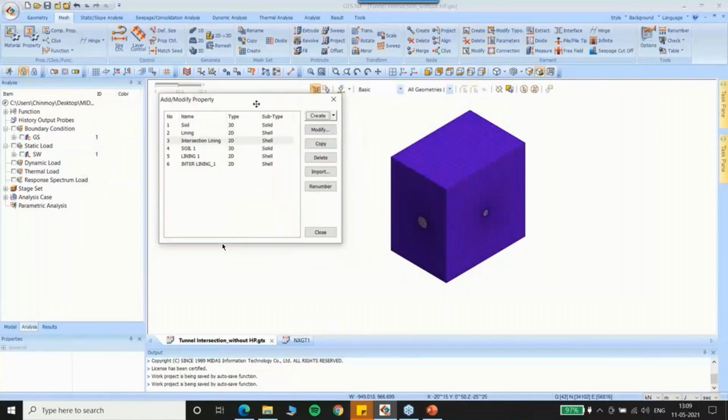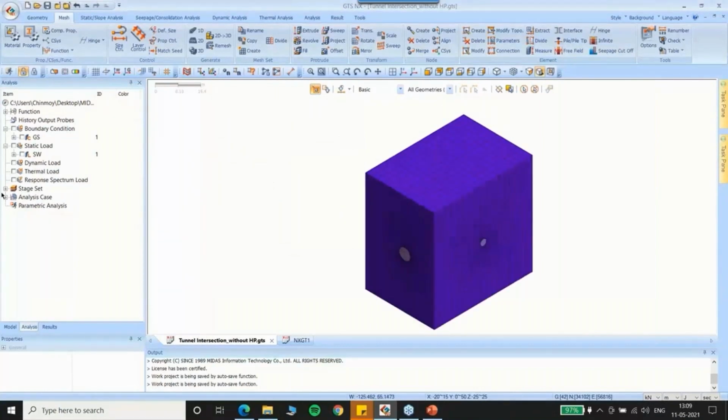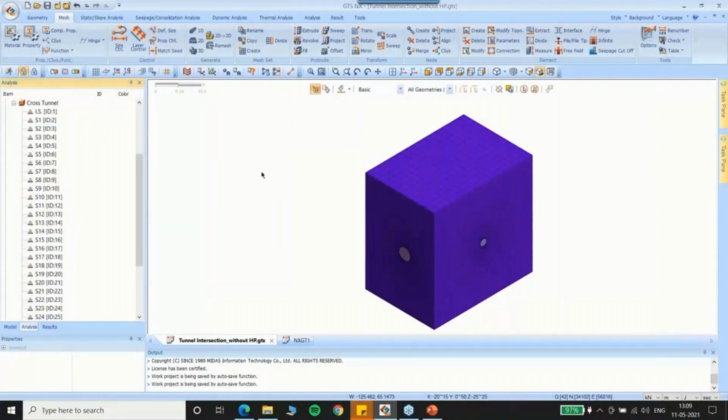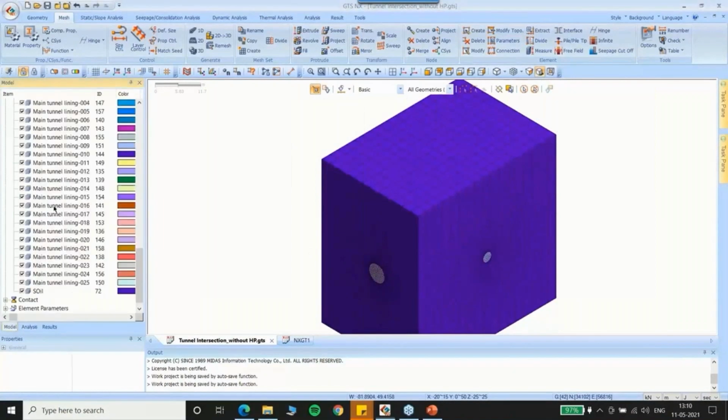So this is how you can create properties. But again, I just displayed it in the model here. You will also get the detailed description of how to create property on the tutorial that will be provided tomorrow. So after that is done, I'll just show you briefly the analysis cases or the construction stage analysis. So to replicate that clearly, I'm going to deactivate the main soil layer.